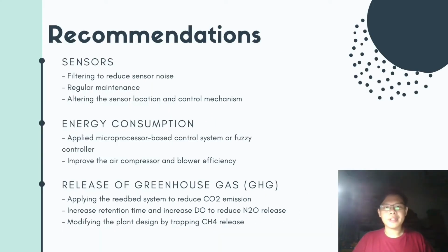Hence, several recommendations can be made to overcome the challenges. First, a filter can be installed on the sensor to reduce the sensor's noise, and the sensor should be regularly maintained to prevent faulty data from being obtained. Next, changing the sensor location and the control mechanism, such as changing the original feedback control mechanism to a feed-forward control mechanism, is quite effective to overcome the time delay for the sensor.